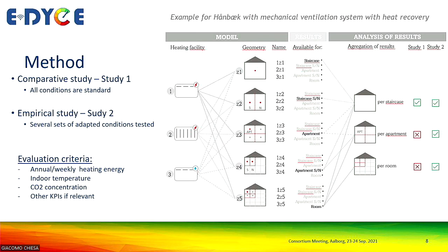Yes, or here. So we can have an electric convector, we can have an electric radiator, or we can model a more advanced way, detailing the water-based heating in our model, and in this way we sometimes can hope to produce better results. We can do a similar approach at modeling the geometry of the model. We can design our models as a one-zone based model.